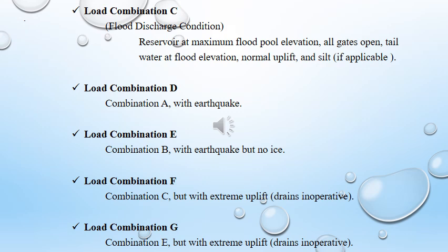Load combination D, so same as load combination A, but earthquake forces are also considered. Load combination E, the same as load combination B, but earthquake forces are also considered. However, ice forces are not considered.